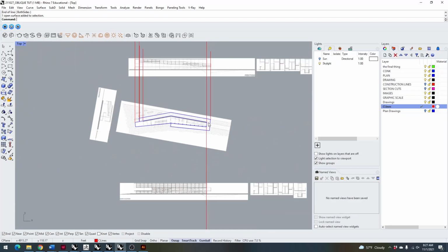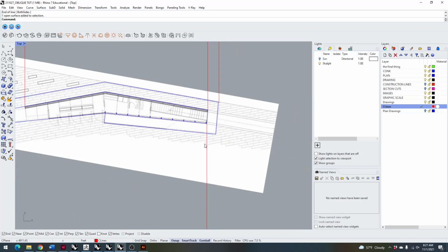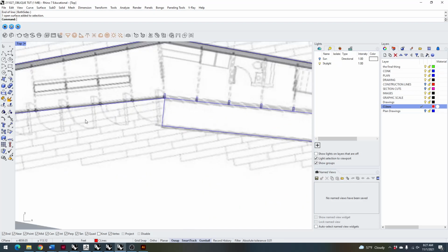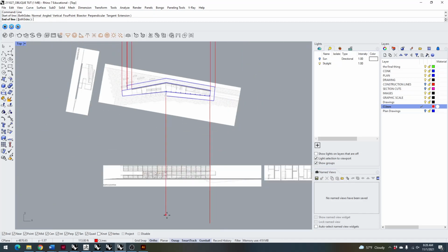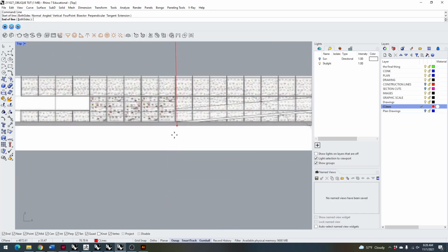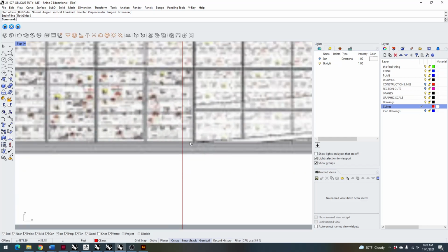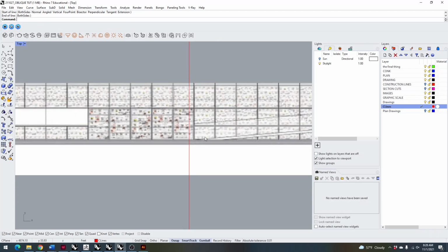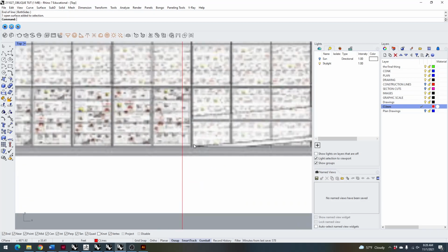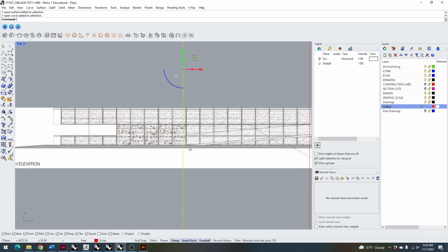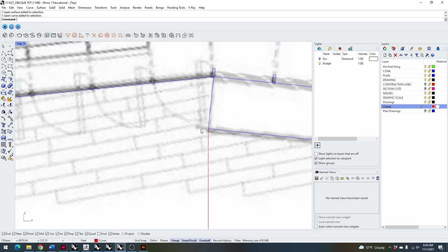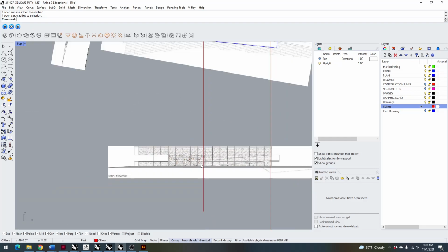And between those points, for example, if we want to find the height of this outermost point of the ramp, we would send a construction line down to the proper elevation that the ramp occurs on, and we can see that the intersection point between the ramp and that line we drew down is 0 height.